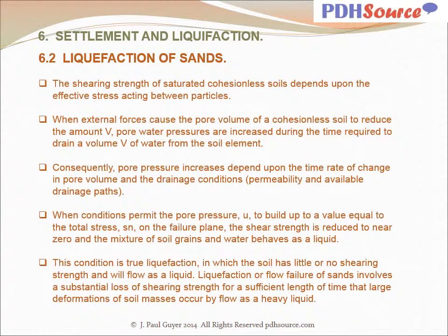The shearing strength of saturated cohesionless soils depends upon the effective stress acting between particles. When external forces cause the pore volume of a cohesionless soil to reduce by an amount ΔV, pore water pressures are increased during the time required to drain a volume ΔV of water from the soil element. Consequently, pore pressure increases depend upon the time rate of change in pore volume and the drainage conditions, permeability, and